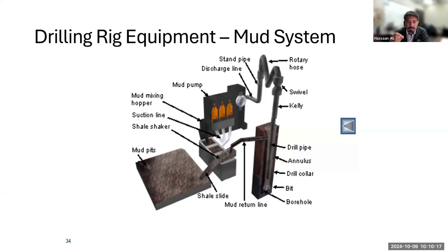The other thing which it actually does, and a very important thing that mud does, is that it applies pressure to the formation so that there is no uncontrolled incursion of hydrocarbons into the drilling string. And you want that because you don't want a blowout. You don't want an uncontrolled incursion of the oil and gas, because then it becomes very difficult to contain. So mud will apply that pressure, that weight, to keep everything within the borehole.